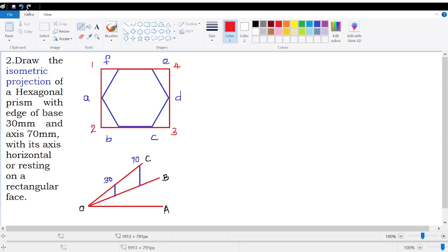So whenever you are getting a question on this, the first step is to draw the orthographic view according to isoscale and then inscribe it inside the smallest possible rectangle. Now we will go with the construction of the isometric projection of this rectangular lamina. We will first create a skeleton, and this is not the actual view. So you have to draw using very thin lines. Use 2H pencils for this.